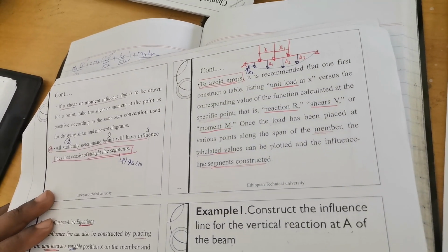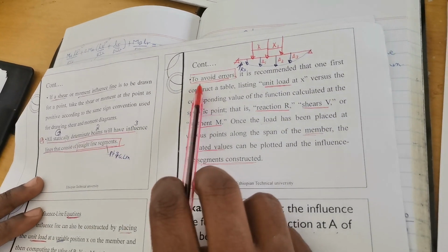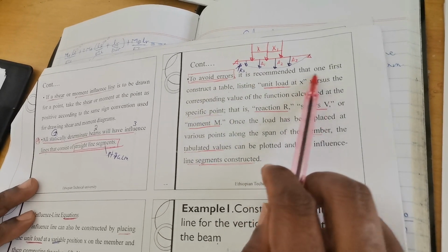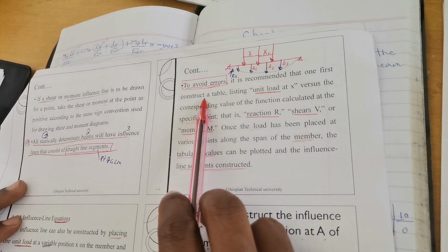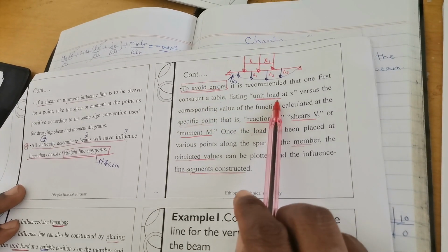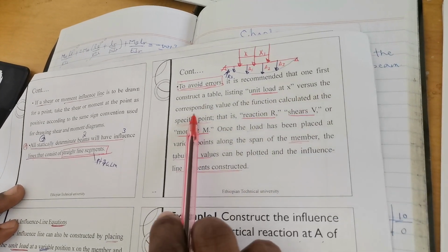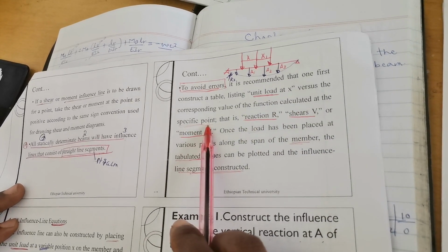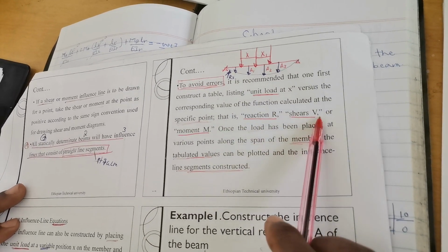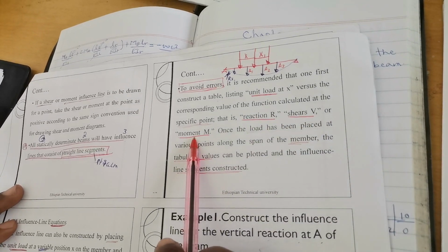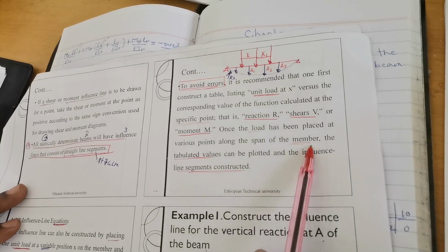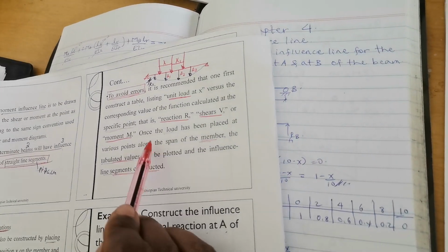Piecewise linear. To avoid errors, it is recommended that one first construct a table listing the unit load at x versus the corresponding value of the function calculated at the specific point, that is, reaction R, shear V, or moment M. When the load has been placed at various points along the span of the member,